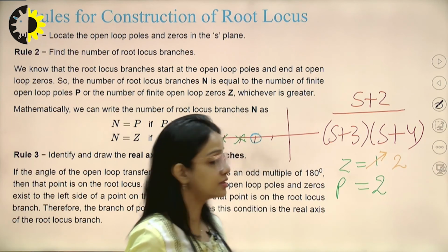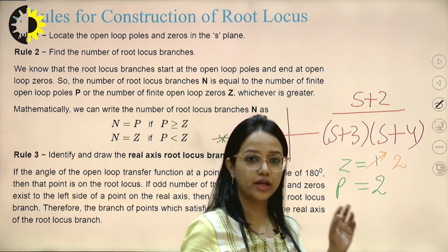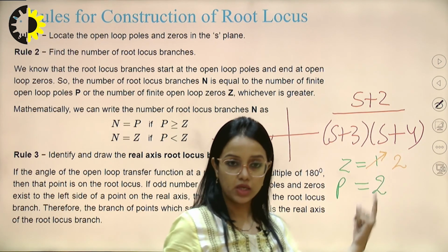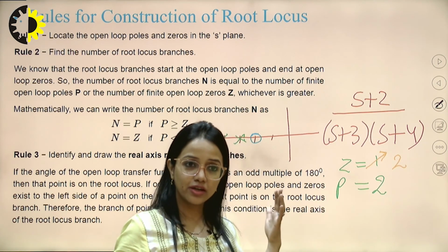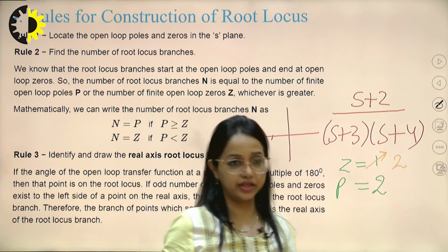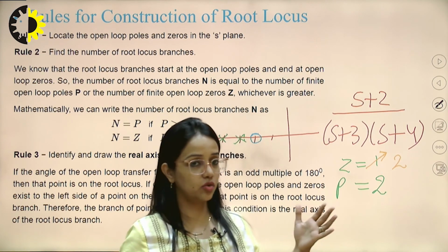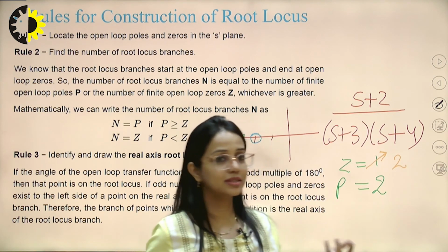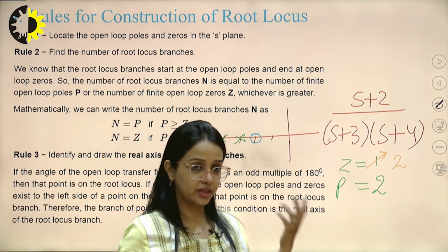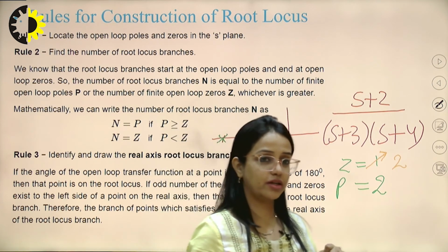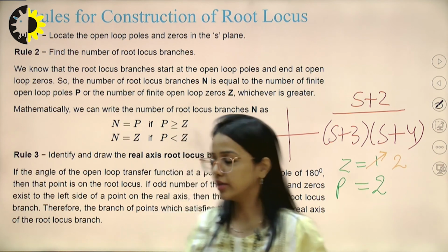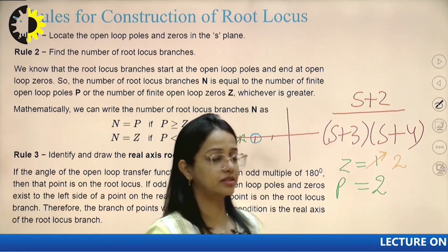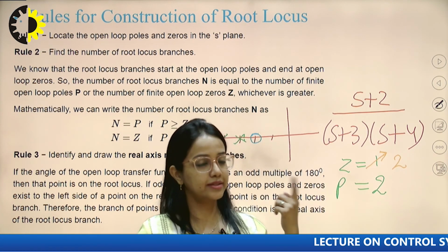We have the same number of poles and zeros for any system. Only the point is, we are not representing that one zero because that is lying somewhere at infinity, and that zero is having no impact on my system. So I'm not representing it. That is what we will study, and the root locus will prove this statement, that yes, we have the same number of zeros and the same number of poles.